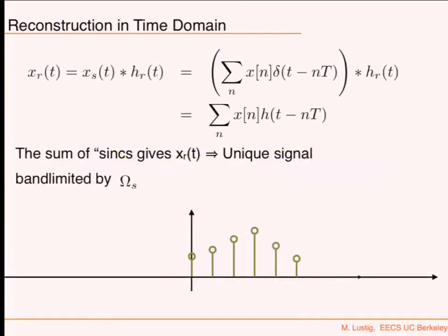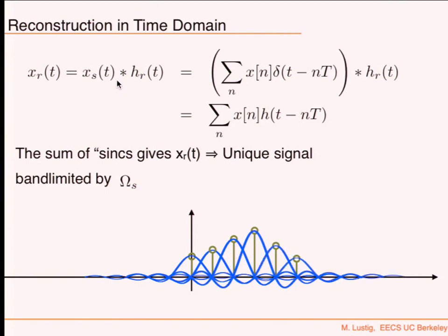Okay. In the time domain, it's a convolution with a sinc, where each one of the coefficients of our signal, basically you put it on top of shifted, scaled sincs. So sinc, sinc, sinc, sinc. The cool thing about this, it's guaranteed to be band limited because it's a sum of sincs. Sincs are band limited. We're linearly adding, a linear combination of shifted sincs. It has to be band limited. Okay. A nice property of a sinc also is that it has 0 whenever the other samples appear. So that's the cool thing.